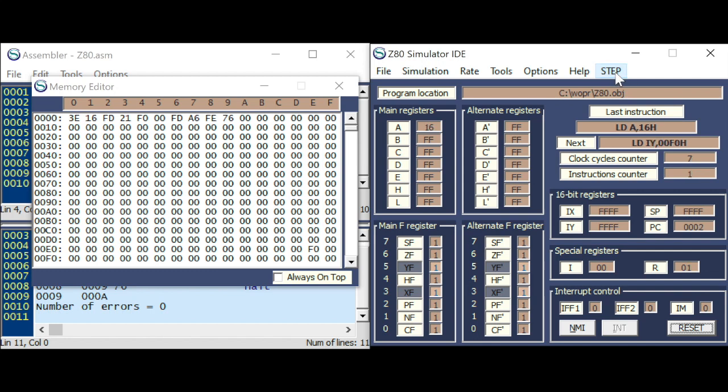Start it again, and this time I want to cut the upper 4 bits. So 6 is left, zero flag is not set, and parity flag is set because 6 is 4 and 2, that's 2 bits, 2 one bits, and that's even.